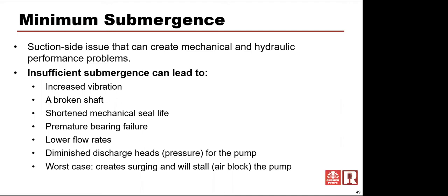And your pressure is going to be reduced because, remember, pressure is a factor of the resistance of the system. So if you have less flow, you have less back pressure in a system. There's less friction loss. There's less pressure drop across a filter or across a nozzle, for instance.